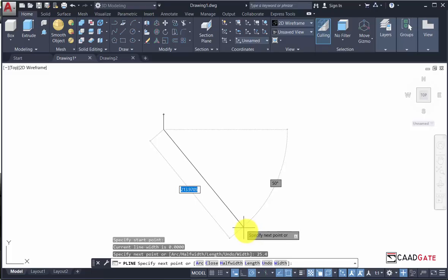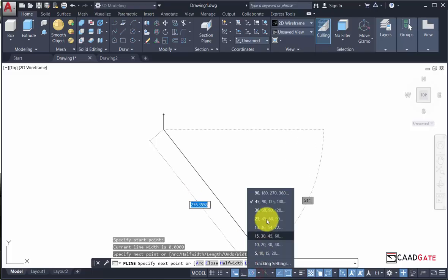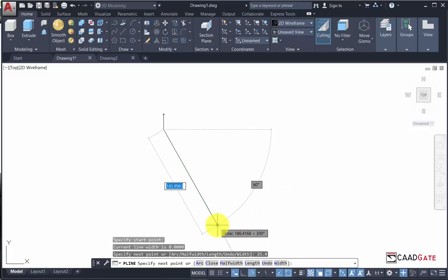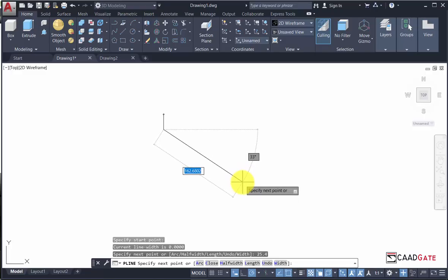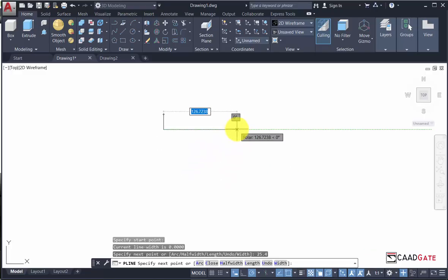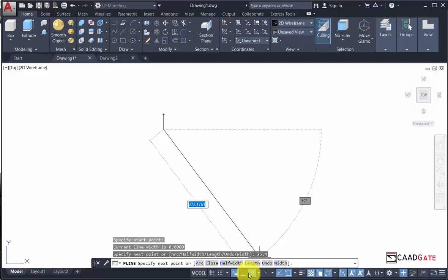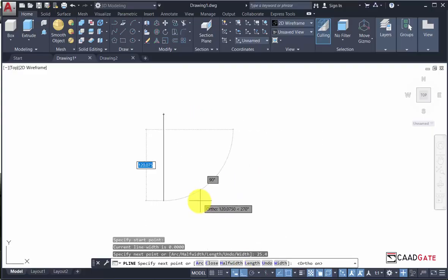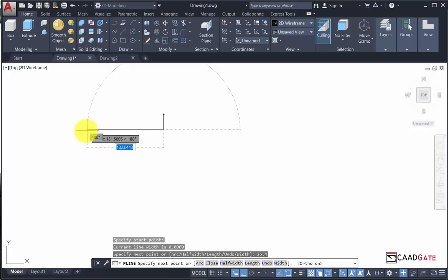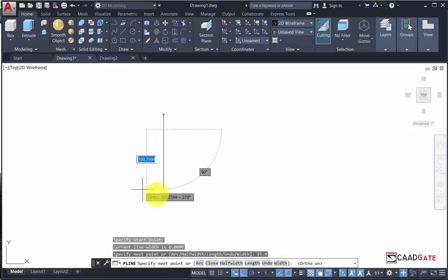If you change it to 30 degrees, it will be tracking multiples of 30, 60, and the rest of them. And let's just talk about the mode setting beside it, the auto mode. If we select auto mode, it kind of restricts your movement to 90 degree increments. I generally don't like to use auto mode.